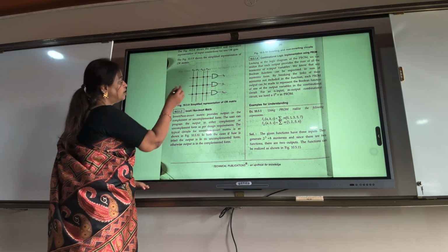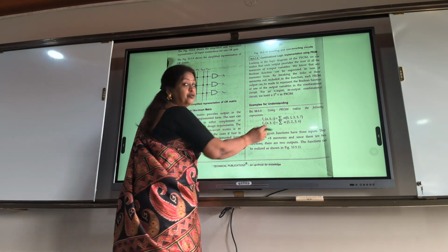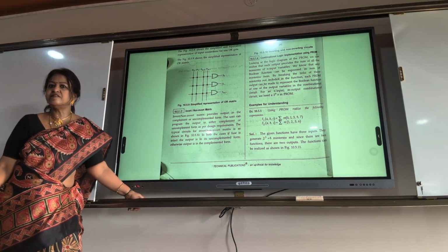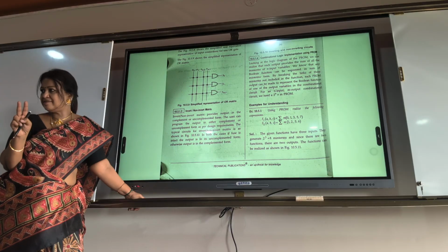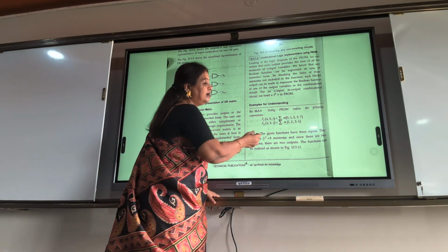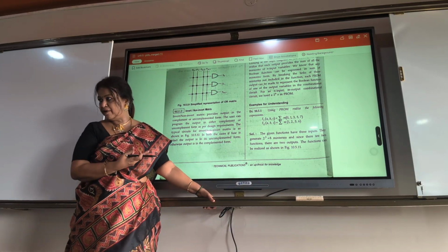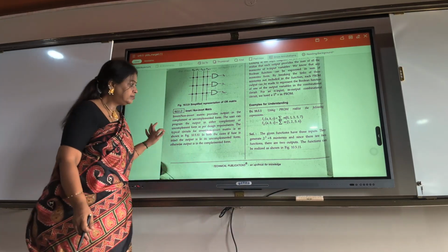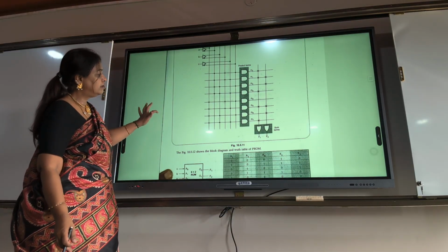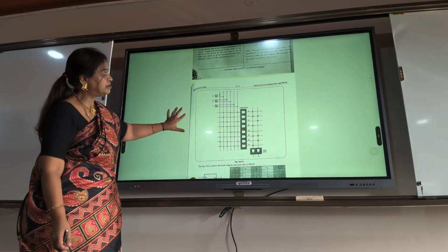The OR should be programmed. So here, let us say this program. F1, F2, 2 outputs are given. What is the size of your word? 2 bits. What is the number of address lines? 3 inputs are given, 2 power 3. 8 by 2 PROM. So this is the program. This is what the answer is for this.